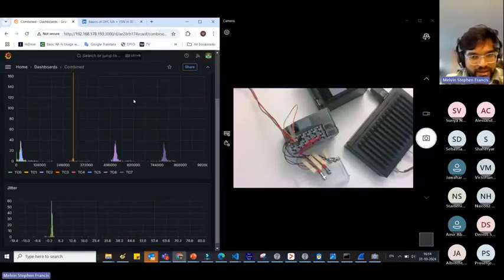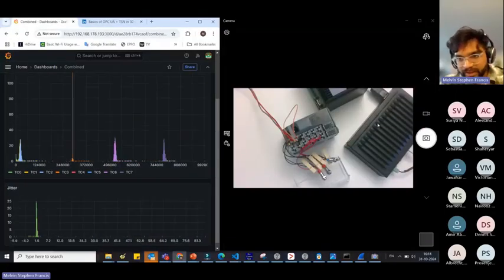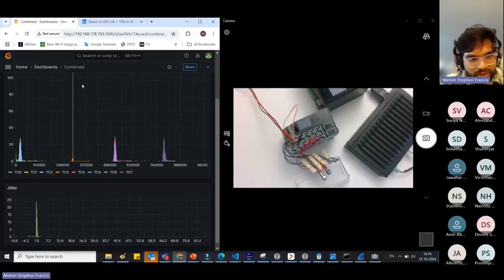So you could see that this particular TQ Systems box is sending the IO signals using the VLAN ID 3. So it's traffic class 3, and it is able to send with a jitter of, for the past 5 minutes, plus or minus 3 microseconds or 4 microseconds.